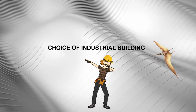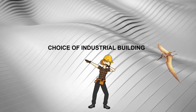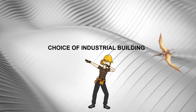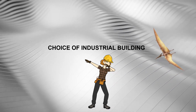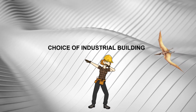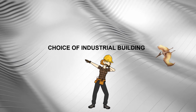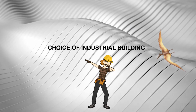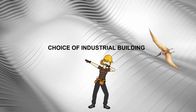The preliminary selection must be made between number 1, a building specially designed for the owner; number 2, a new factory largely built of standard structural components; or number 3, the adaptation of an existing building. The latter may be either an advanced unit built as a speculative development or a unit which has been vacated. The location of internal columns and the internal headroom are always important, and consideration of these requirements alone may determine the choice.